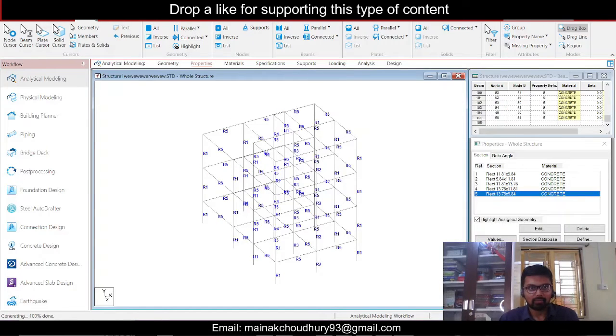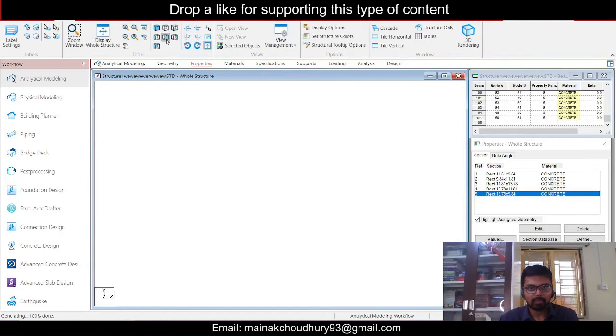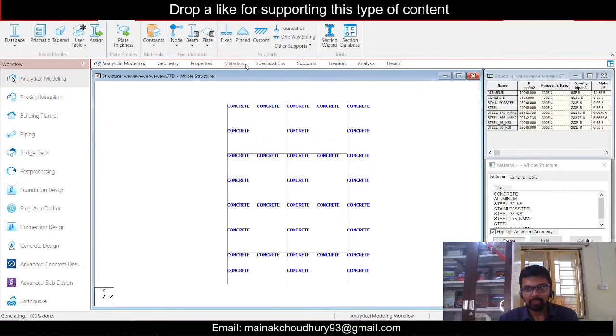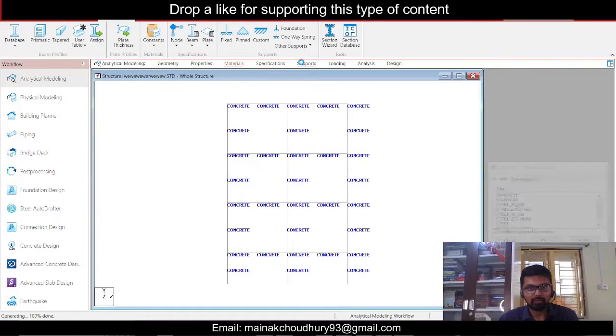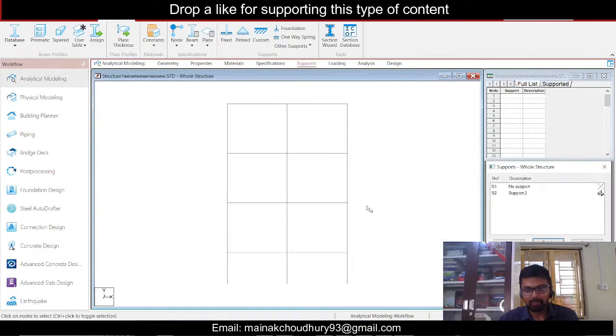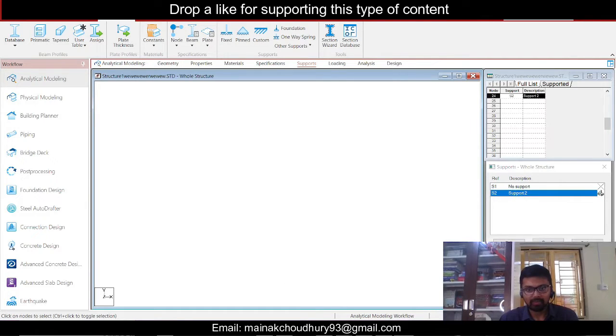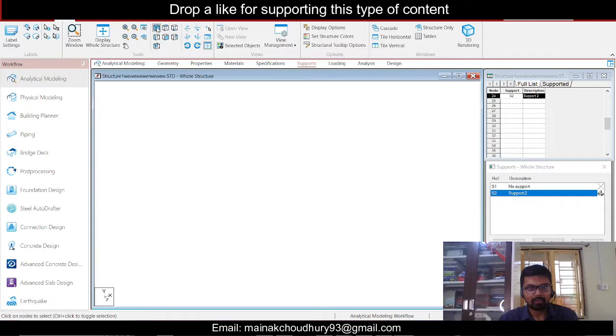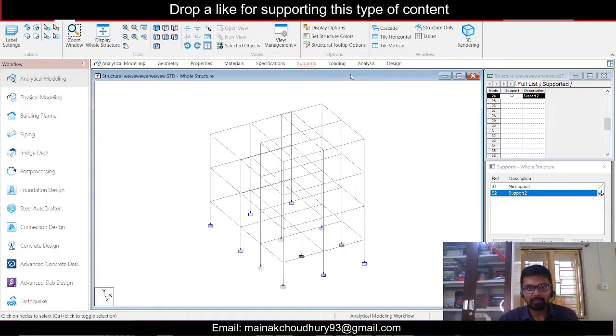And then let's go to the front view. After that we'll go to materials. The material is already concrete, everything has been assigned. Go to support directly and create a support, fixed support, and click on add and select this and this support first. After that select the base, assign and yes. Okay, you can see in the 3D view that all have been assigned fixed support.